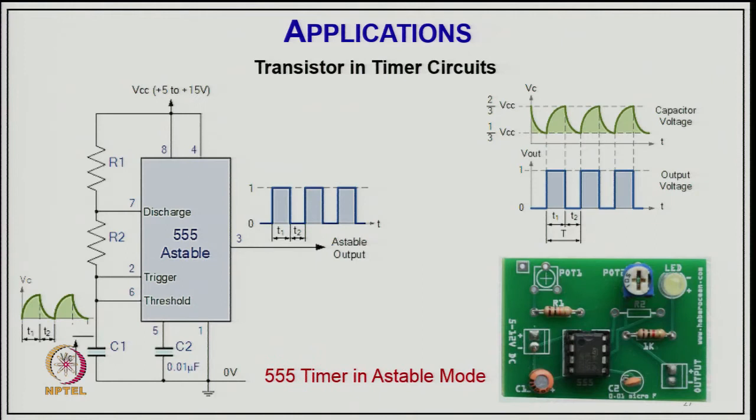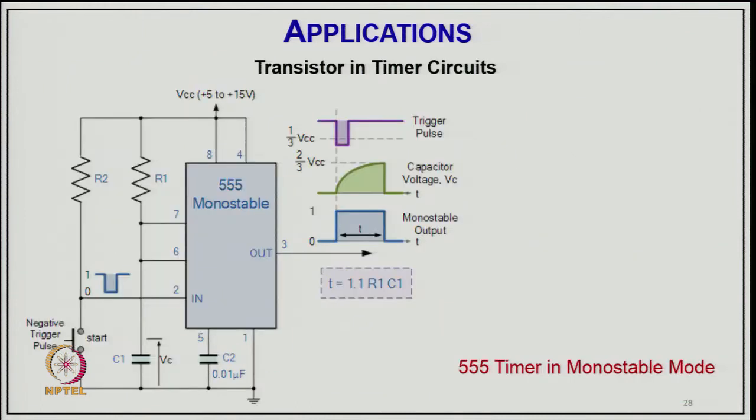And you can design many circuits from this chip, you can design an astable multivibrator, and you can decide how much the duration or frequency should be. I mean, this is the internal structure of this virtually. You have to put external components connected between the different pins for the purpose of deciding the frequency and duration of the pulses if we want to develop it, and this is the typical complete circuit of your 555 chip timer you are using in astable mode as an astable multivibrator.